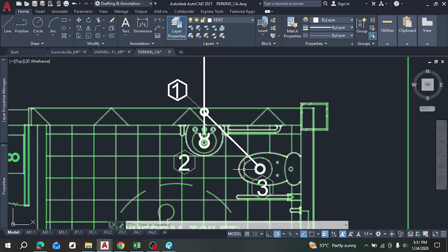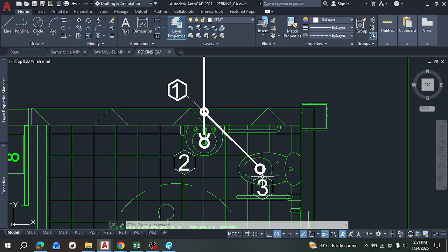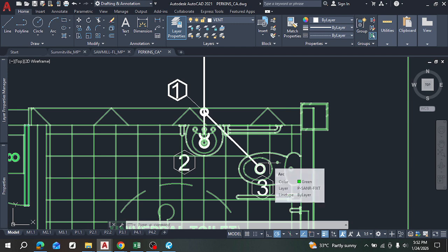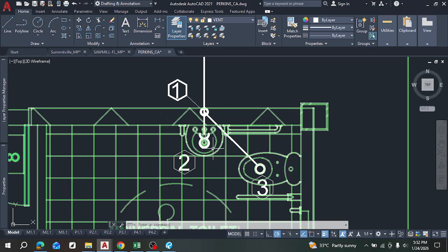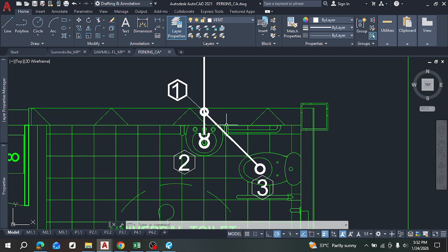In many cases, it's usually advisable to ensure that your sewage line passes into a wall, preferably the back wall of that space. But in this case, I did this because this basically comes out into the ground. In some models, it goes into the wall, so that is another alternative. But I just imagined going out like this around, and it did not sit very comfortably with me. That's why I chose this, right? So now this goes here, and along that drainage line, there has to be a vent in a wall. That's why it must always enter into a wall, right?